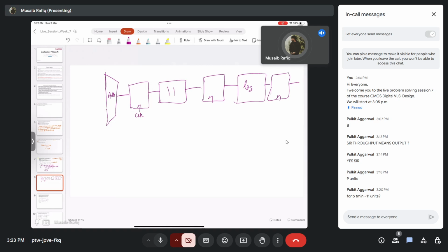This causes computation for one set of input data to spread over a number of clock periods. When the clock period starts, first the addition block computes and shows the result in the register. Then it passes on to the absolute value block, that is the mod block, and the adder block computes the adder operation for another set of inputs.